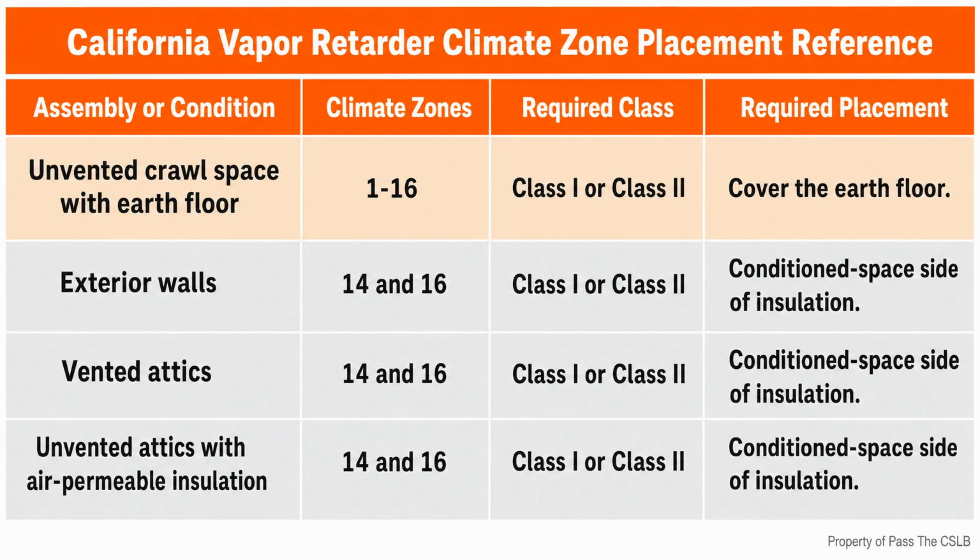I do not turn that rule into universal instruction to add low permeability layers everywhere. An assembly has to retain an appropriate drying path, and product facings can change vapor performance. If the plans, energy documents, product data, and field condition do not agree, the general decision is to stop and resolve the conflict with the responsible designer or authority before concealment. More layers are not automatically more protection.